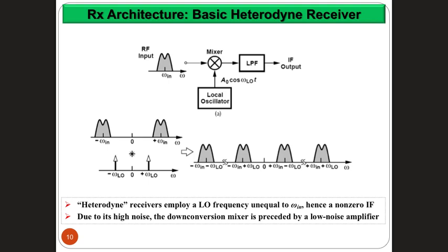After taking all these considerations into account, and similarly the duplexer and so on, we start now looking at different architectures of receivers. The first receiver that we'll look at is called the heterodyne receiver. The basic heterodyne receiver brings the signal to an intermediate frequency. It doesn't bring it from its modulated frequency down to zero frequency, or down to its baseband representation. It brings it to an intermediate frequency.